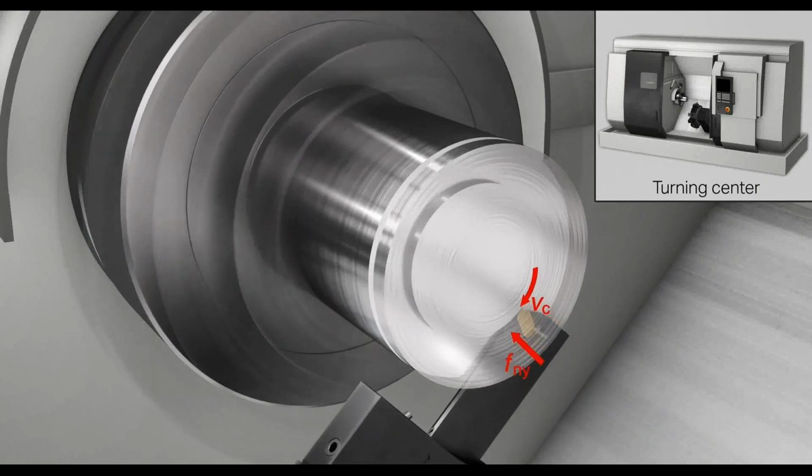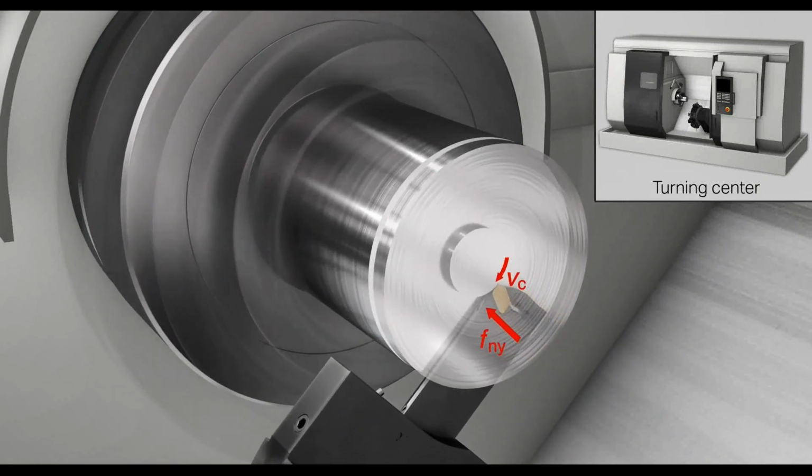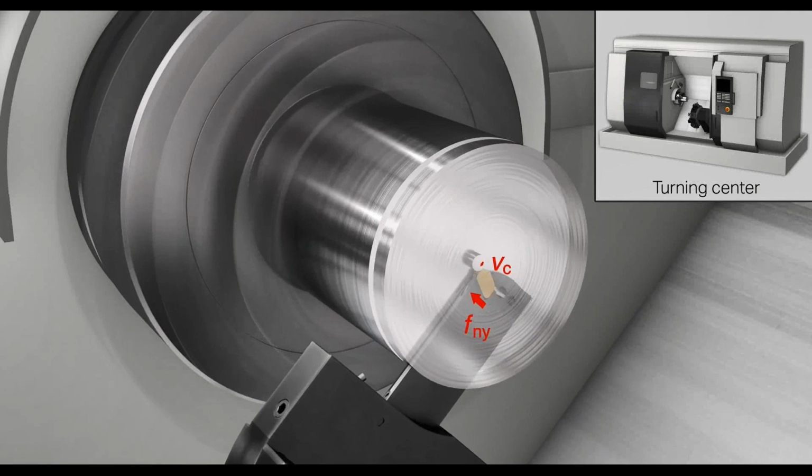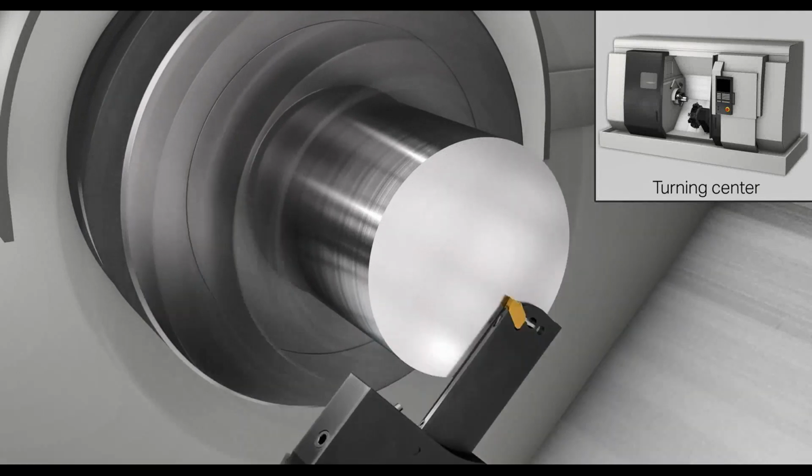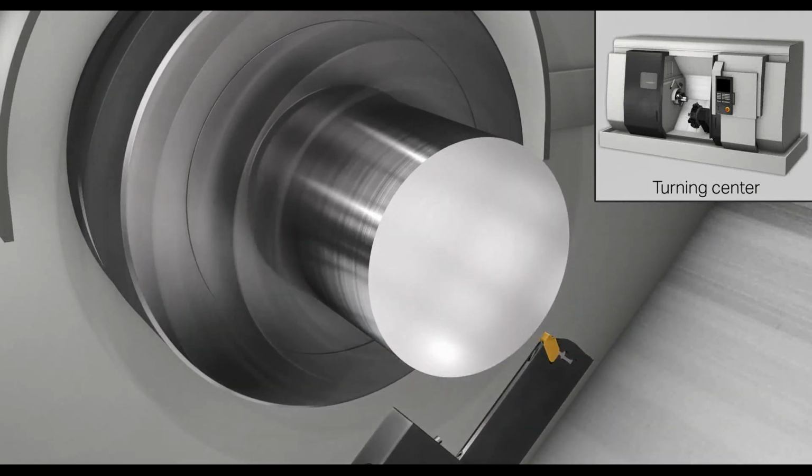One thing you need to note is when you're actually putting these tools in the machine, it is very important that you follow the setup. On the blade, they're laser marked on how to touch it off and what offsets you need to put in, because the positioning of the insert is not where you would think it would be. So there's two different offsets, depending on the blade that you're using, that you need to put in when you're applying these tools.